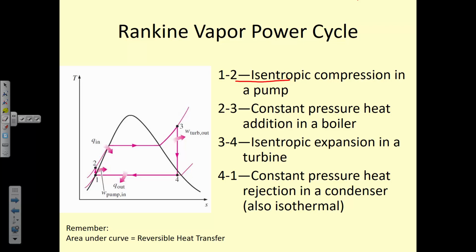Yeah. So it's like superheated steam, which is a very dry steam, meaning it's very, very hot, it doesn't even look like steam. It's not translucent as you're looking through it, it's not foggy, you can see through it very easily, but it also scalds all of your skin off if you touched it, so you don't have to get too close to it. So dry vapors are very dangerous, because with steam you can often see it coming out, and with the dry vapor you can't, and so accidents do happen because people walk in front of a leak or something like that.